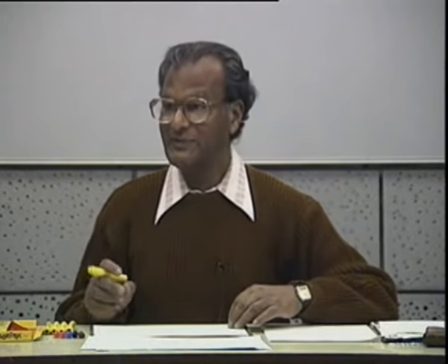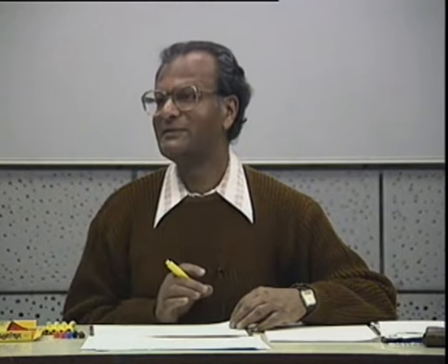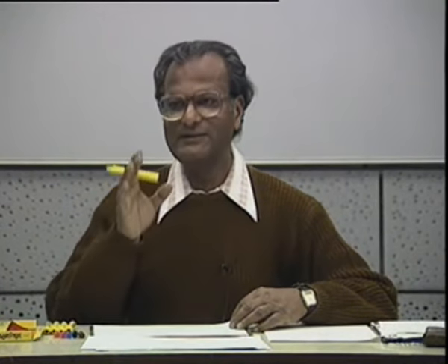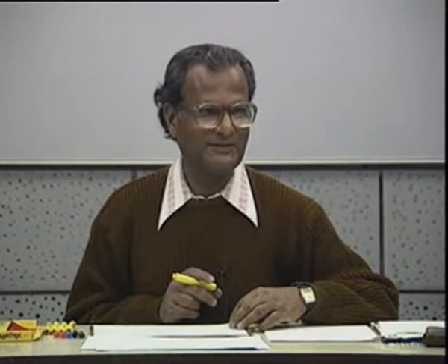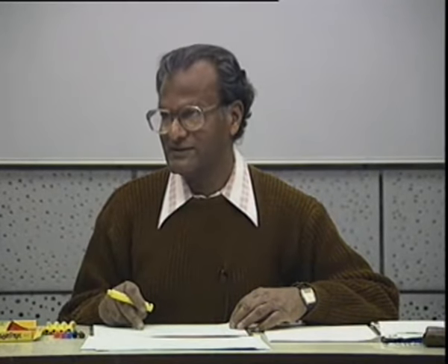The reason is clear. RS1 and RS2, we didn't make them equal. We didn't make VS1 and VS2 equal. So there can be a difference voltage between the two bases. If they are absolutely identical, then of course our purpose is served. We have an ideal differential amplifier. It is to take care of the non-ideality that we are going into this analysis.